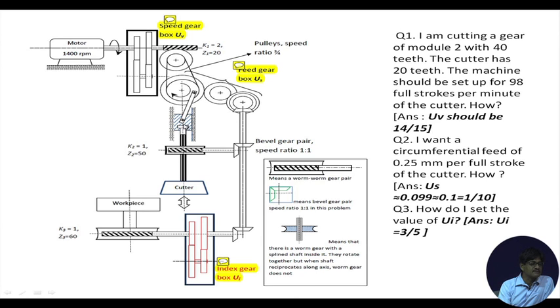Now, why doesn't the cutter shaft come out of the assembly here? Because it's still inside a rotational space, within a hollow surface of revolution. So, there is no problem. It remains in position, moves up and down, and also rotates inside this embedded space. So, now we have rotation of the cutter added to its reciprocation. As previously planned, the cutter is now reciprocating as well as rotating.